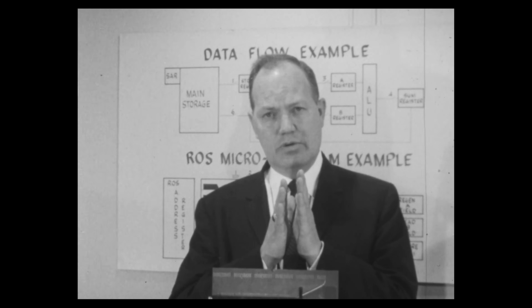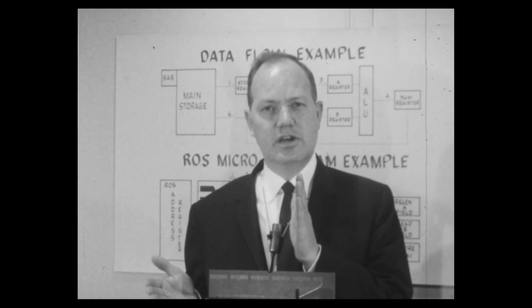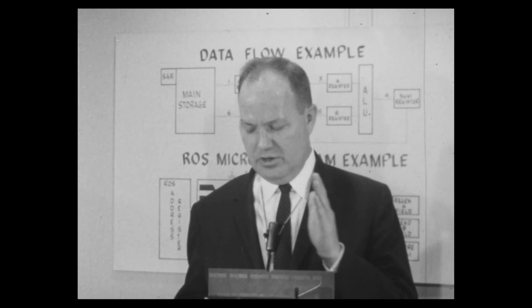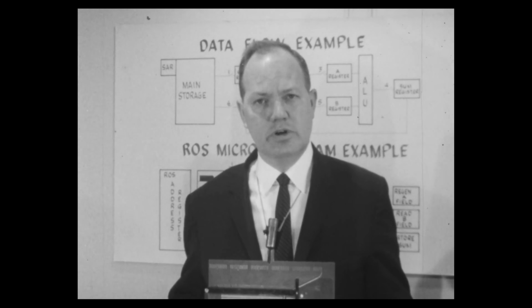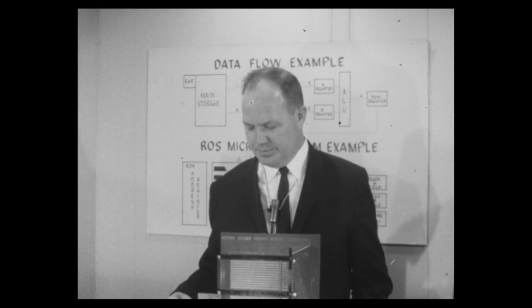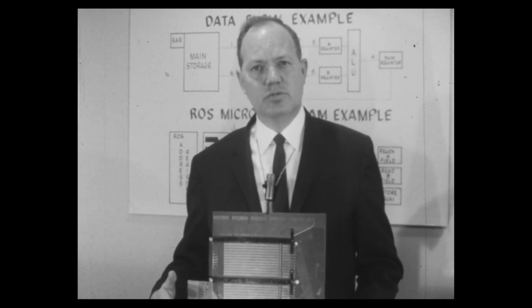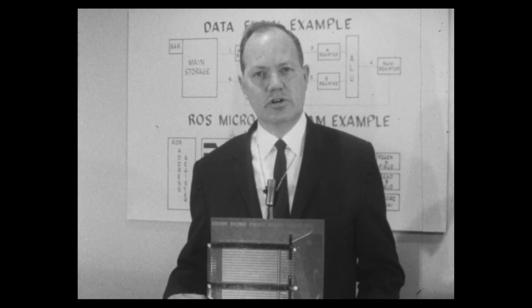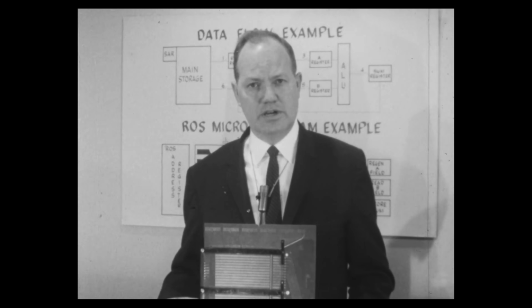If we have a pulse there, we say that we have a bit, or a 1 condition. If I perforate one of the plates or remove it, then I say I have a no bit or a no capacitive pulse. Consequently, we are able to develop the 0-1 binary bit pattern required for the machine operation. The engineer determines what pattern he needs at a particular sequence in time of the machine operation and sets this up in the cards. That then becomes a permanent read-only storage that the machine will constantly utilize.